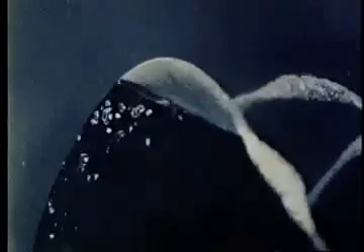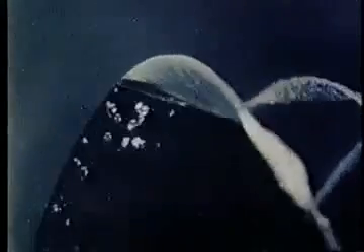Let's look at the propeller model again. At this point, we want to emphasize the role of the ambient pressure. The pressure is low and the propeller RPM is constant. Notice the cavitation on the blade faces as well as in the tip vortices. The pressure is now being increased by raising the pressure of the gas above the water surface.